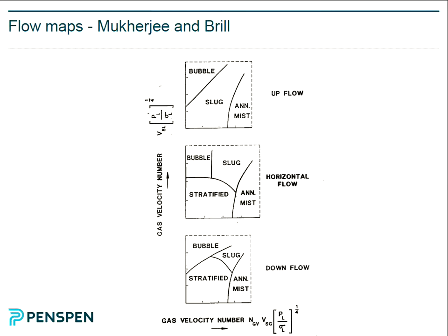So to do any kind of analysis, you need some way of predicting properties. Generally speaking, this will be included in the multi-phase flow program. So it's knowing what properties are at any one time. And there are two sorts of ways of predicting properties. One is using a correlation or black oil model, which is where they've actually made physical measurements and then come up with a formula or a curve fit that replicates the properties of the measured product.